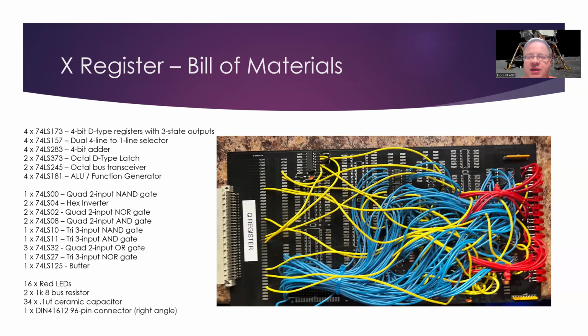I do have enough cards built, as well as the backplane, that we can start issuing control pulses and getting some functionality to occur, so we can transfer data from one register to the next. We haven't built the actual control pulse logic yet, so we're not going to be able to automatically run instructions on the AGC, but we can at least manually load data into registers and read data out from registers onto the write bus, and start to test these boards out and make sure that they're working the way that we expect.